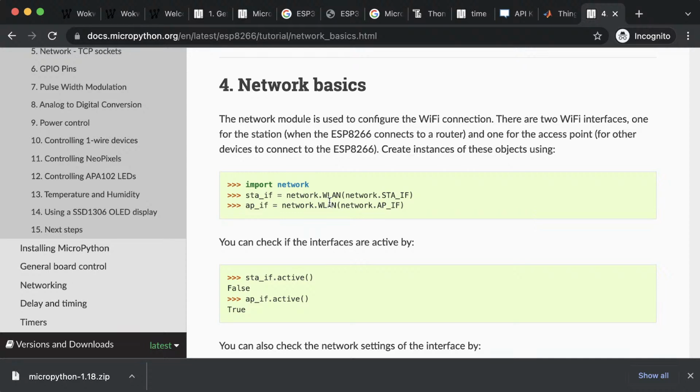Dual mode says that you can act as a station as well as access point simultaneously. So your mobile phone is acting as an access point for the rest of the devices which are going to connect to that hotspot, whereas it is also acting in station mode to get connected to your router, so that it can gain access to the external internet, the World Wide Web. So our ESP32 is just like that, and today we are just going to connect our ESP32 to a Wi-Fi. Our ESP32 will be acting as a station, and a Wi-Fi router has an access point. We are going to connect to that. So we will be using the STA mode, or the station mode.